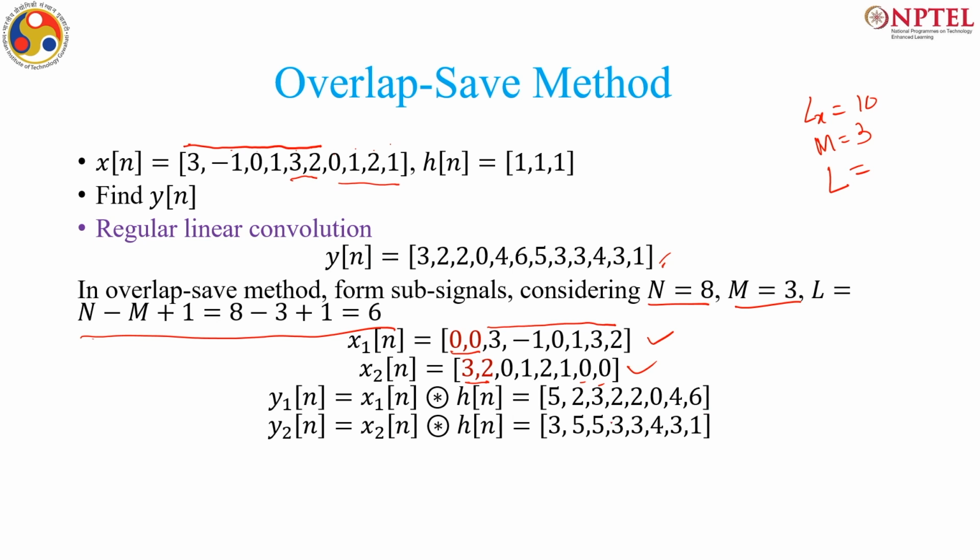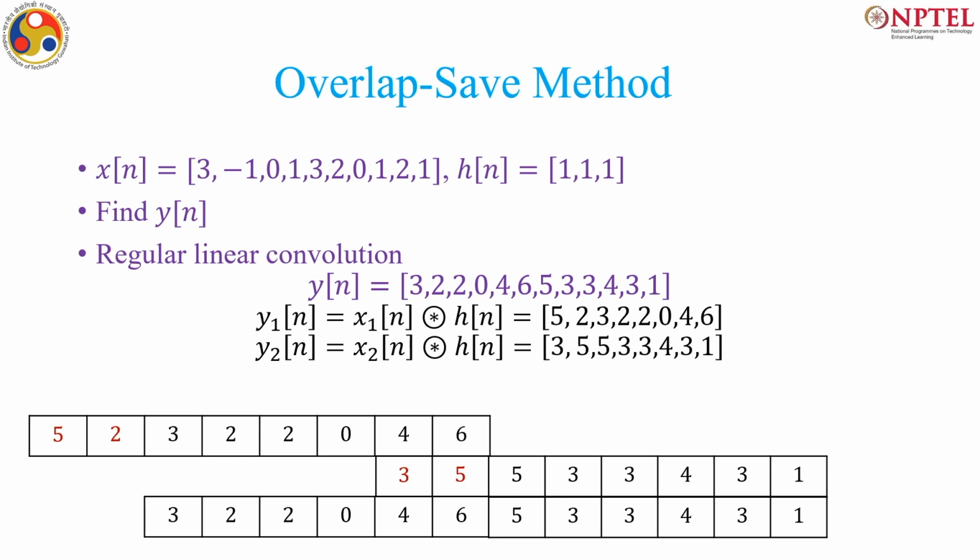Now, I will do circular convolution. In the time domain I am doing this circular convolution because this is just an 8 point sequence, but practically I want you to know that the circular convolution will be done as a multiplication in frequency domain, and this conversion to frequency domain will be performed using FFT and IFFT, which will take n log n complexity. So, these two will be your result. So, again I see this is my y1 n and this is my y2 n.